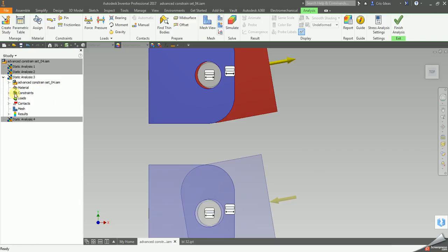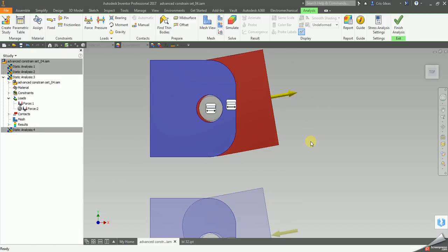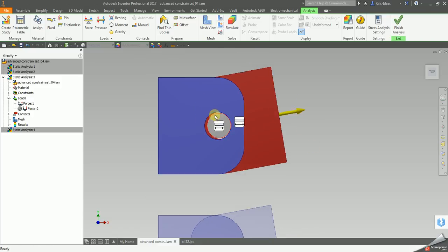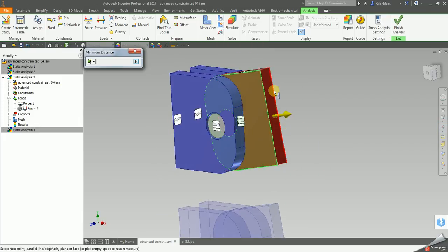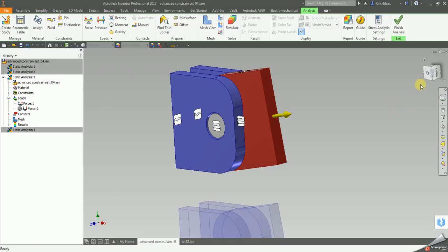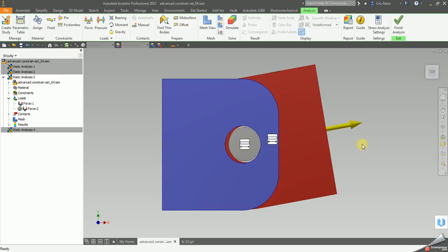Now, if we consider the load here is 10 kilonewton, 10 kilonewton is really 1 ton of force. This pin is 18 millimeters in diameter. This plate is 10 millimeters thick. So loads applied here are very small compared to the capacity of these elements, and I have it solved.